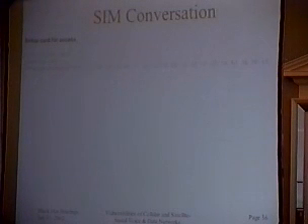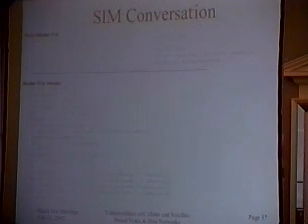So let's take a look at how we talk to a card. The first thing you do is you power up the card and you send it a reset. And what you get back is an ATR, or an answer to reset. And that data tells you about the card, tells you what it is, tells you how to talk to it and what to expect. So then you say, okay, I want to look at the directory structure of the SIM. So you request to the SIM, I want to look at what's known as the master file, which is kind of like the root directory. And that will tell you what's in there and everything else that's going on. So the underlying data in blue is decoded for you underneath there. So when you read that file, you get a file header and it tells you what's going on with that master file.